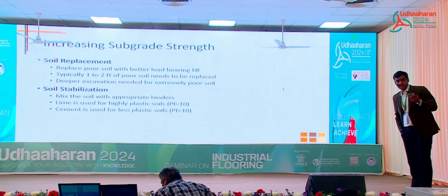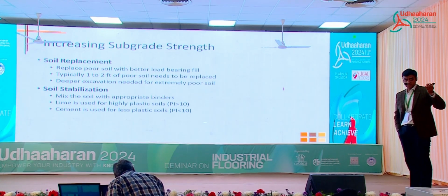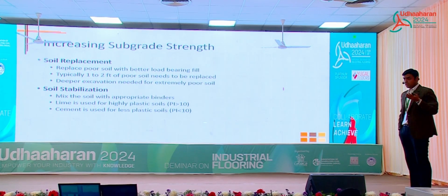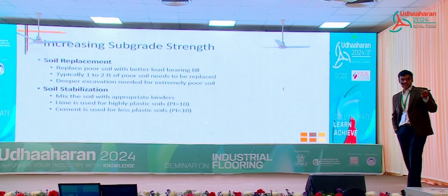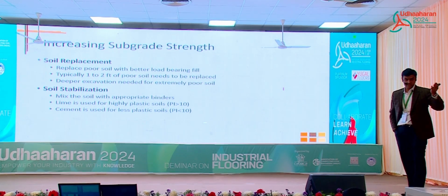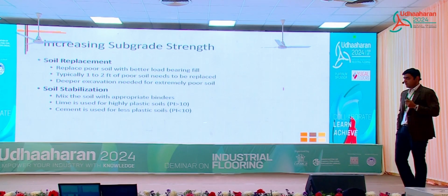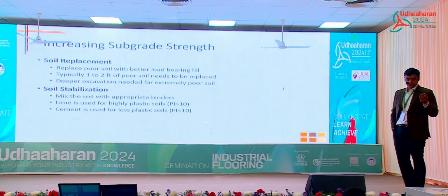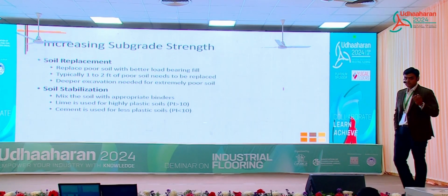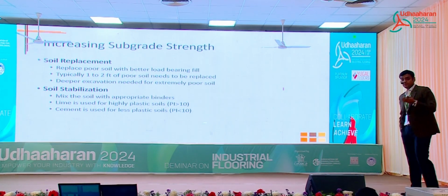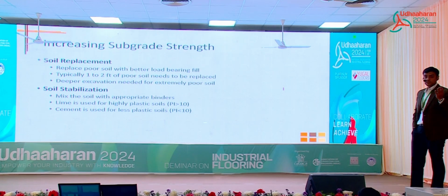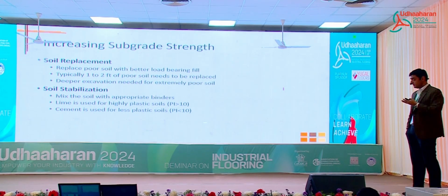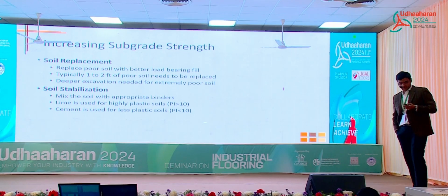Two places where we have experience. We have worked across 15 states in the country, and we have dealt with lots of materials. Kolkata and Vijayawada stand out in poor soils, and Shastri sir also mentioned Gujarat. In Calcutta, they tried to mix fly ash, and the floor settled horribly. We didn't do the floor, but they had about 200 mm settlement in the floor. So that is what poor soil or poor soil stabilization can do to you. Vijayawada is similar, black cotton.